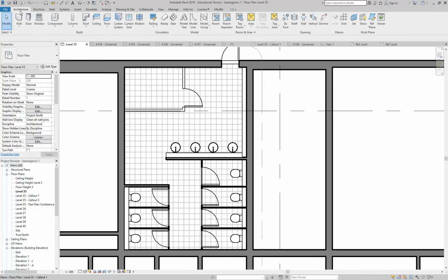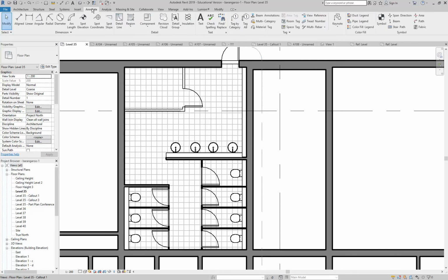So you've got a few different options. You can draw lines that are 3D using model lines. Right, and that's okay if you're happy to see them in all of the views. But often, with things like this, you don't want to see them in your 3D views or the other views. You only want to see them in the view that you're drawing in. So it's more realistic.